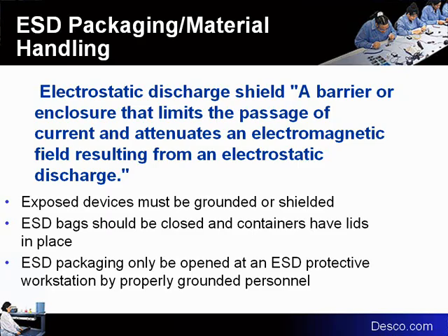The same would apply for the ESD tote. An operator at an ESD protected area with a wrist strap would be able to place items inside the tote. Once inside the tote and covered, you would be able to disconnect from ground, take that tote to an inventory area or its next task, so long as before it's opened again, it is done at an EPA with a grounded operator.